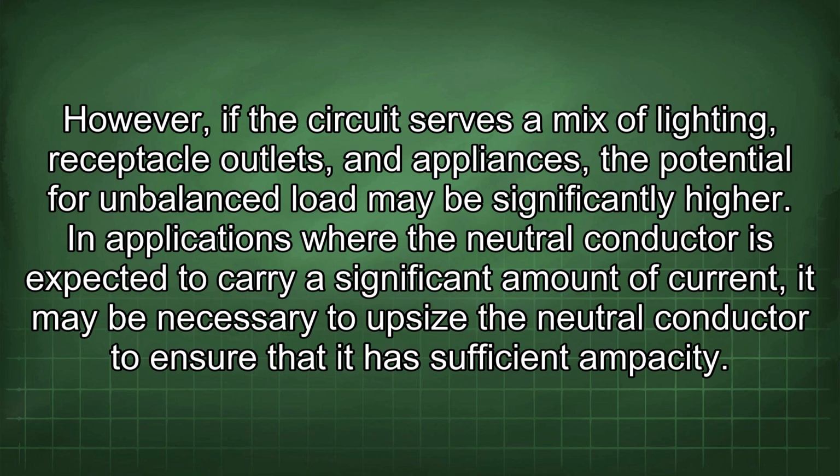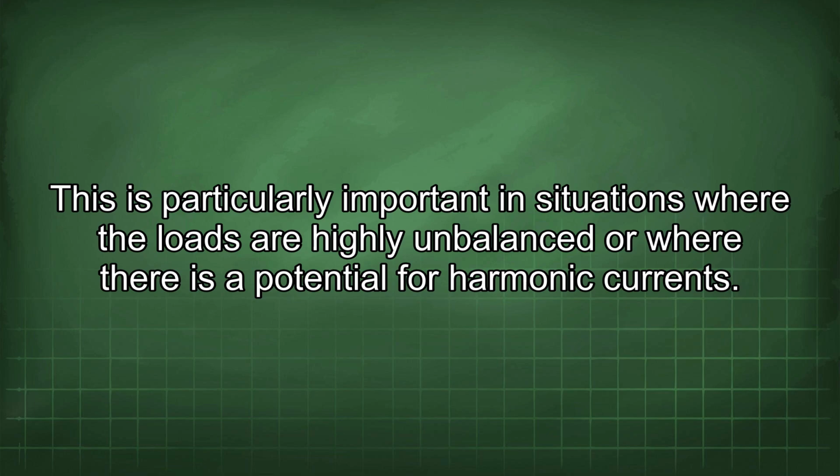However, if the circuit serves a mix of lighting, receptacle outlets, and appliances, the potential for unbalanced load may be significantly higher. In applications where the neutral conductor is expected to carry a significant amount of current, it may be necessary to upsize the neutral conductor to ensure that it has sufficient ampacity. This is particularly important in situations where the loads are highly unbalanced or where there is a potential for harmonic currents.